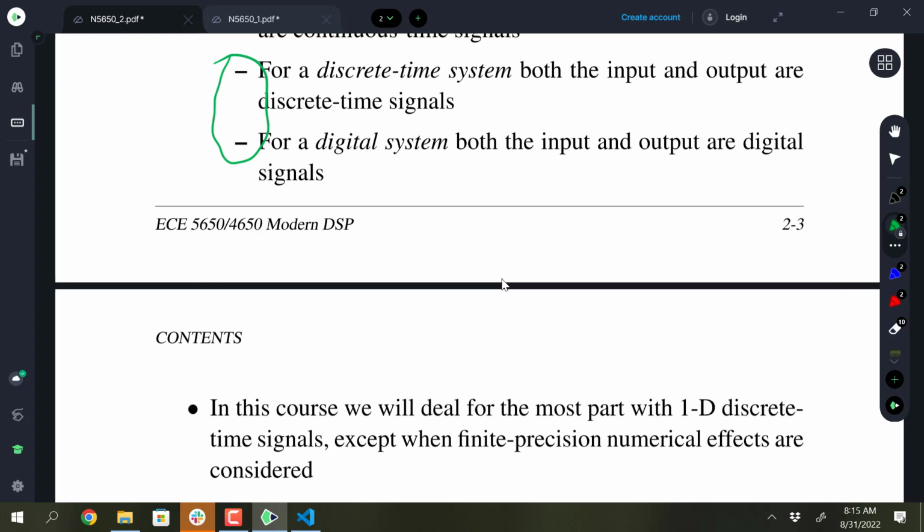Delta sigma is a technique that was developed quite a few years ago now to take a 1-bit A to D converter that's oversampling and produce 16 bits of resolution out of it. Does that seem pretty special? I say special because a quantizer that only has to quantize between a +1 or a -1, if it's oversampled, you can actually fill in values in between and go up to 16 bits of width.